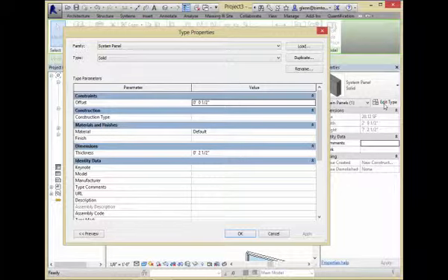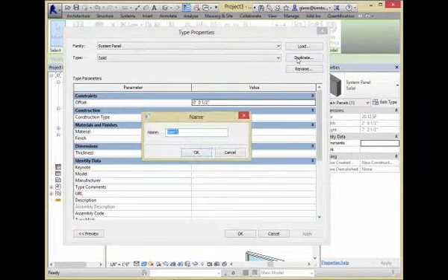I like copper panels. I'm going to make a copper panel type and put it in my library so I can use it in all my jobs from here on out. So here's how they do it. Solids, you'll see, are defined with this nice material called default. That's the kind of gray, drab material that doesn't really have any material properties, it's just some sort of solid surface. If you would like to have some different panel types, what you do is you say duplicate.